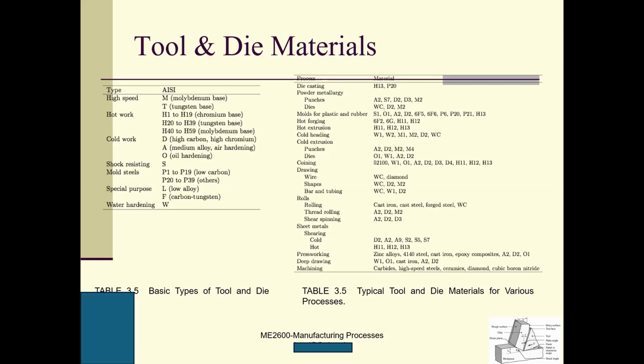You want to get the final product by compressing, extrusion, or these kinds of things. The severe deformation, that is metal forming. The difference is whether you have chip formation or not. If there is chip formation, machining. No chip formation, metal forming.